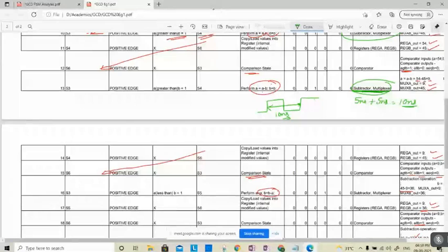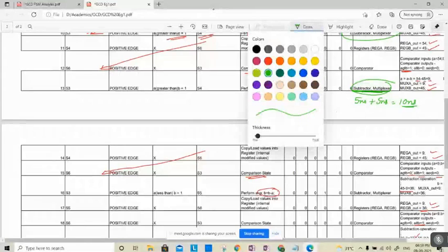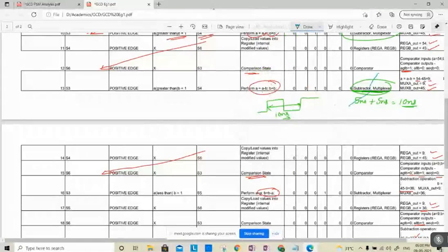Now what I am saying is, think of a procedure through which we can split this into separate clock cycles. Perform the whole subtraction here and perform multiplexing in the next clock cycle. Then can we reduce this 10 nanoseconds to 5 nanoseconds? Can we do it then? Yes sir. Yes, all the people in the group.